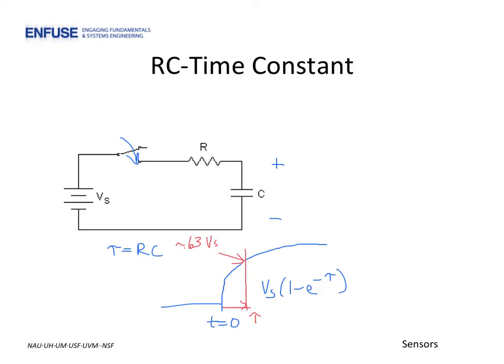So, as either R, the resistance of the circuit, or C, the capacitance of the circuit, increases, so will the response time of the circuit, and the longer it will take for the voltage across the capacitor to reach the source voltage. Furthermore, we know that the low-pass cutoff frequency of this circuit will also be dependent on these component values, that is of R and C, specifically that omega is 1 over RC.